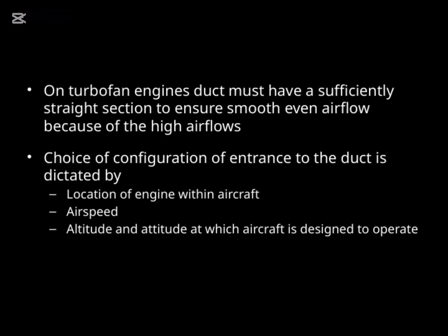Second, we have to consider the airspeed. At higher speeds, airflow behaves differently, so the duct configuration needs to accommodate those conditions to maintain efficiency. And third, the altitude and attitude at which the aircraft is designed to operate are also key. These factors affect air density and pressure, which in turn influence airflow behavior and duct design choices.